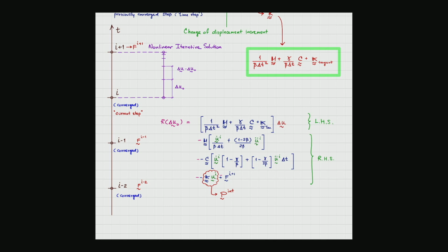When nonlinearities occur, it starts from a small point and then it spreads. So if the mesh size is big, that means the sensitivity to the nonlinearity is going to be lower. You pick it up later. Sometimes you don't even pick up the nonlinearity, whereas the better model picks it up. And that depends on the skill of the user of the finite element program. At least you need to understand the nature of FEM before you use it.